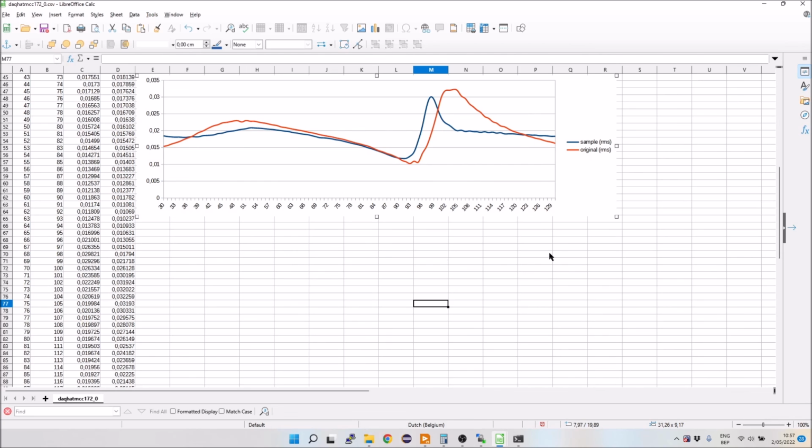So the red one is the wild first measurement, where the input was always 500 millivolt peak to peak. The second one where I compensated, it does compensate a bit. You can see that the blue line is more linear or less non-linear than the original one, but perfect it isn't. And then again, let's forget about what happens after the 90 Hertz. I believe that part can't be properly controlled.